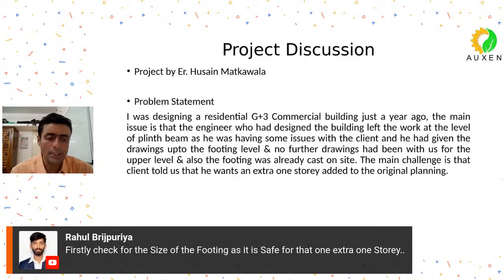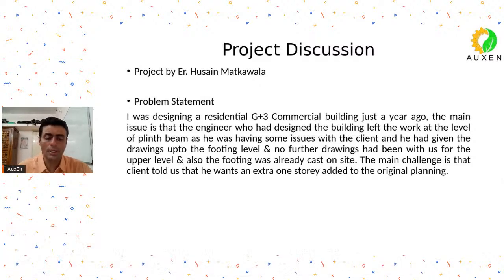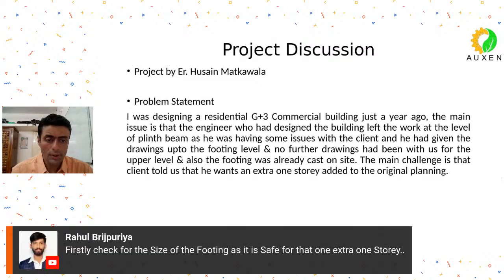Mr. Rahul is saying that first check the size of footings, as to whether it is safe for that one extra story or not. Yeah, so footing checking will come later. First, you need the loads from the superstructure. To get the loads from the superstructure, you need to have some calculations behind it, isn't it? You need some background calculations. So those you can do by preparing some computer model, let's say. So you prepare some analysis model, and then you apply the loads, run the analysis, and check the capacity of footings. First of all, if your footings are not safe, what are your options? Yes, tell me. If your footings are not safe, let us say if the footing is unable to take that additional one story load, you see that the bearing pressure is being exceeded, then what do you do?